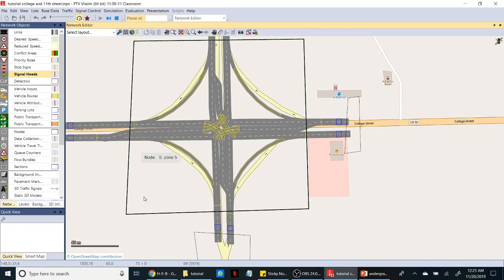So after completion of the simulation, you need to check the vehicle performance delay, total delay, and summation of delay for each individual. I'll show you in a second after the time is done. It's about to reach 3600 because we set the time for a 1 hour simulation.